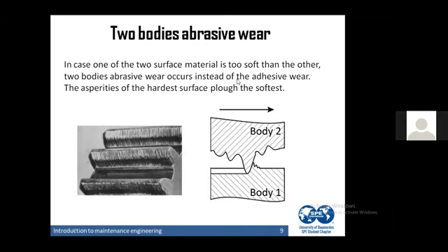So those two types of wear will explain why in the beginning of life in equipment, we have such high failures, because in the beginning, we will have a lot of asperities, a lot of roughness, because the equipment is new. So we have a lot of abrasive and adhesive wear. Because of that, the manufacturing companies always have their standards to keep this wear in control.